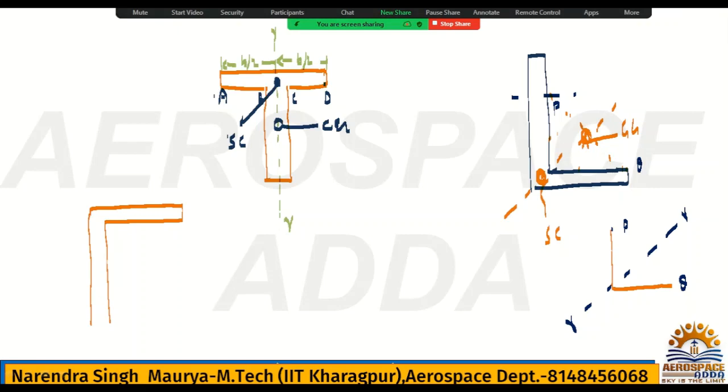In fact, if you calculate CG, you may get the result. When I taught moment of inertia and CG calculation, I said take any textbook for the practice. If you solve for the L section, you may get CG here. And for this type of section, here also CG you may get somewhere here. This will be the CG location out of the structure. And where will be the shear center? The shear center will be like here, somewhere here. This will be the shear center. Is that clear?